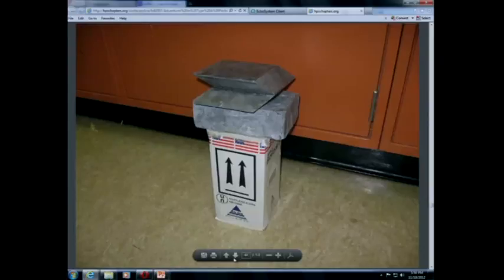And then this is the loading testing. This loading test is equivalent to a force of at least 5 times the weight of the package for at least 24 hours, simulating the damp package being at the bottom of a stack of packages. And in this case, they've just got an equivalent to 5 times its own weight sitting on top of it. And it'll sit there, and this is after it's been wetted.